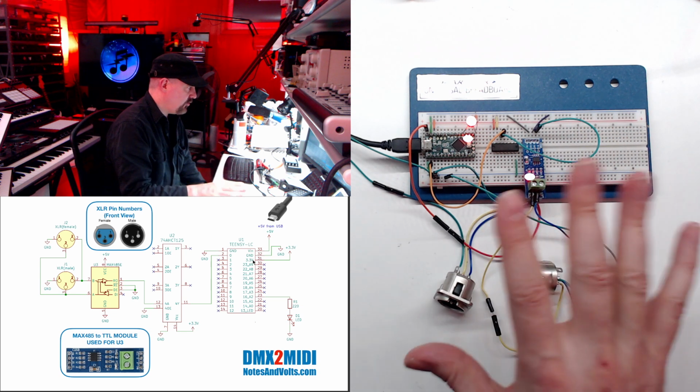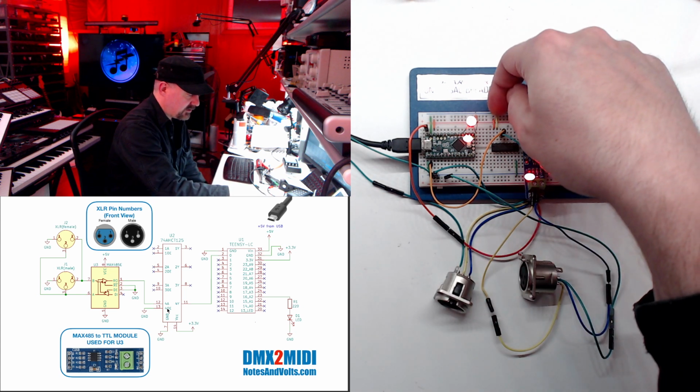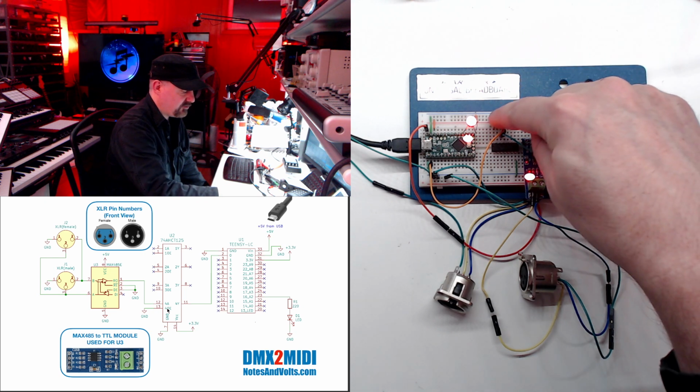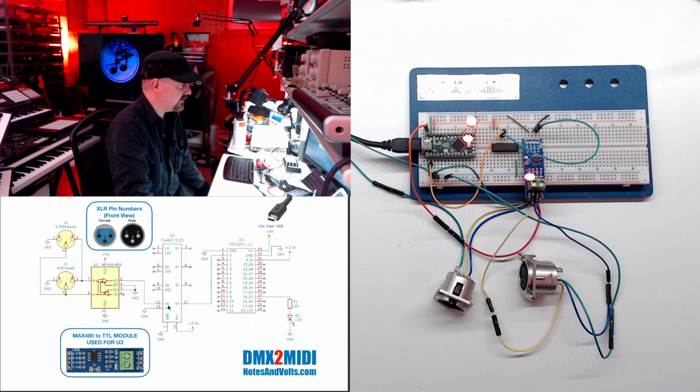Like I said, this is a quad buffer, so that means there's 4 different buffers in one chip. We're just going to pick one. I chose buffer number 4 for this example. Now these buffers have 3 pins. It has an enable pin, and this is ground enable, so we have to tie the enable pin for the buffer we want to ground. That's where I've got this going to the ground strip. Our buffer 4 has 2 pins, an A pin and a Y pin. I don't know why they're called that, but that's what they're called. The A pin is going to be your input.